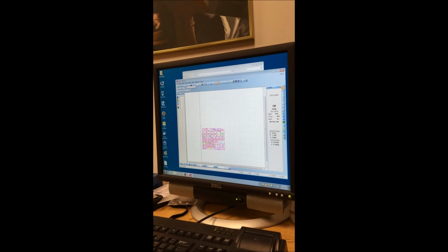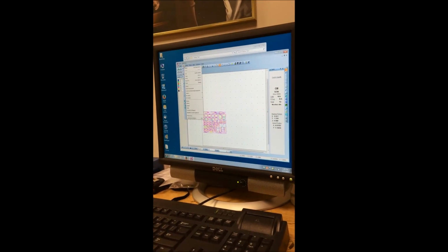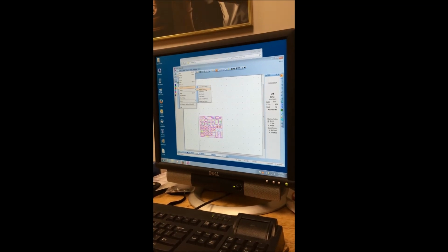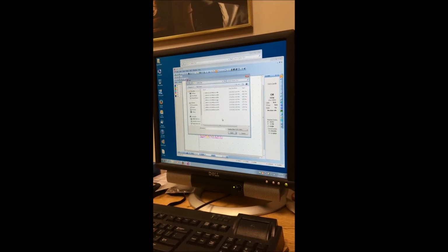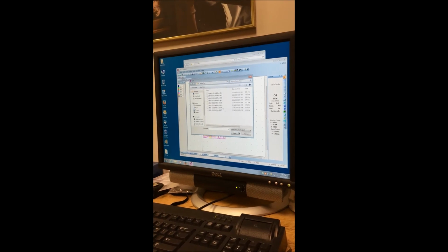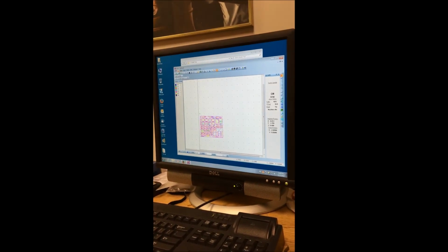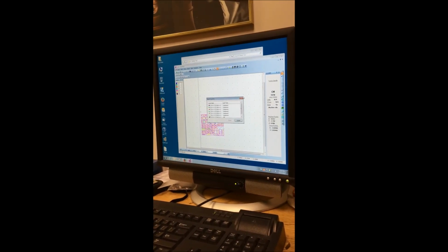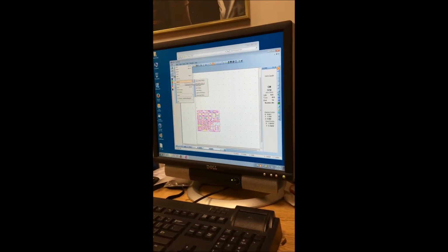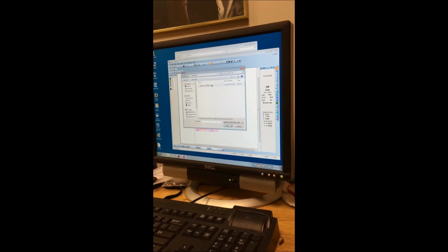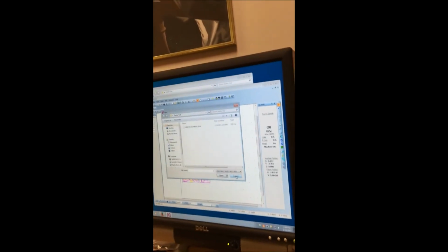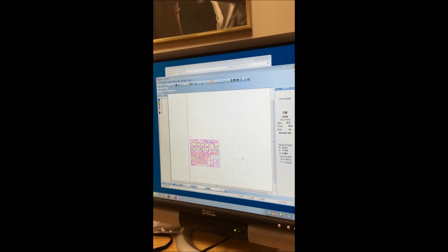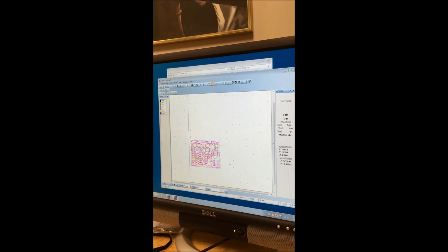The Gerber files are exported from EagleCAD or however you can get them. And you do that by going to File, Import. I do Gerber files first, and then I already have them saved here. I already imported it, so you would select and open. And then you would do the same for the drill files, which is right here. I hit export. You would import the drill files, same thing, that's created in EagleCAD or whatever similar program, and that brings everything into IsoPro, and IsoPro communicates with the actual QuickCircuit machine.